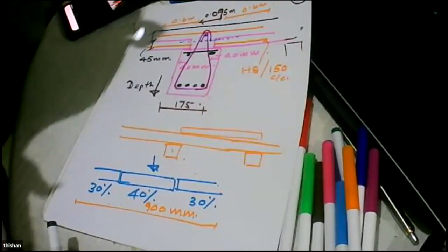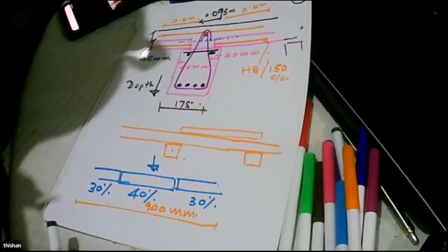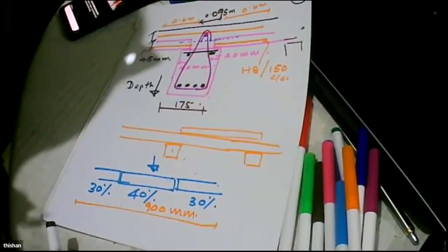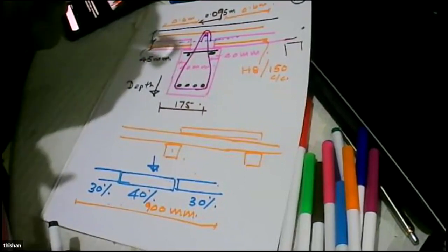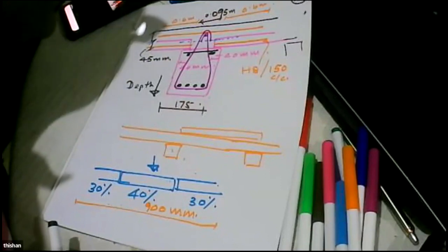Okay, clear, sir. And that's all, I think, the questions. Yes, one more question is there. Is the imposed load enough, since the above slab load is acting during the casting? No, during casting we have props. That is why I said transferring.